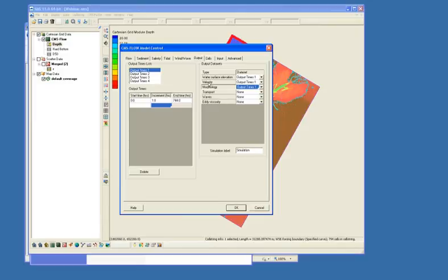So a lot of times we get our velocities at 6-minute intervals. What you could do there is associate velocities with output times 2 and then set up a new time list for every 6 minutes for the entire run, and then your velocity output data set will contain those values in it.